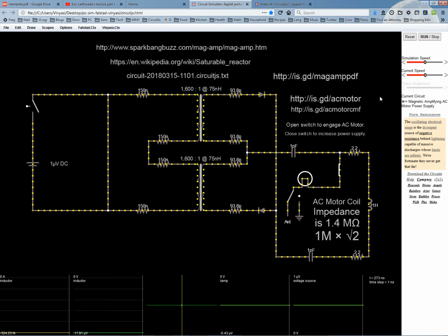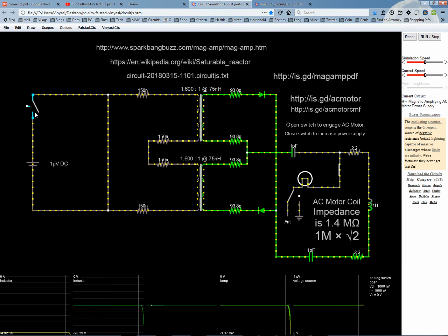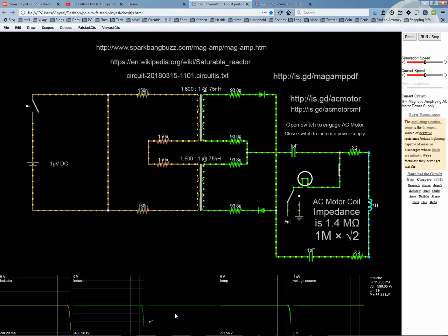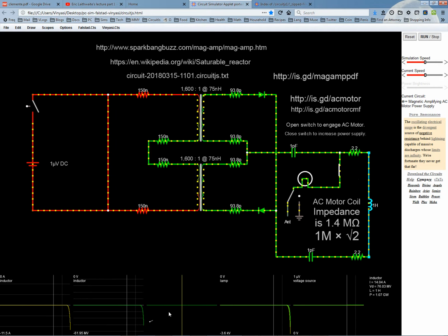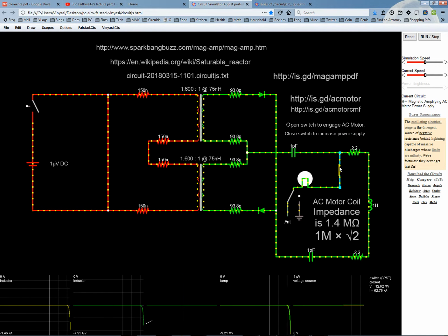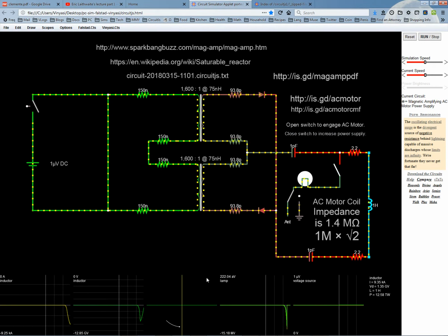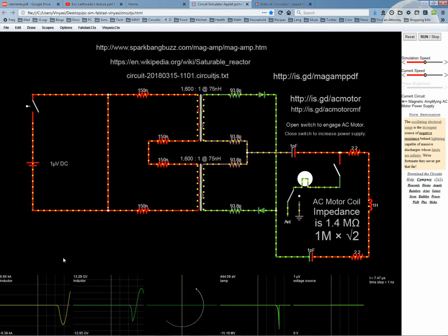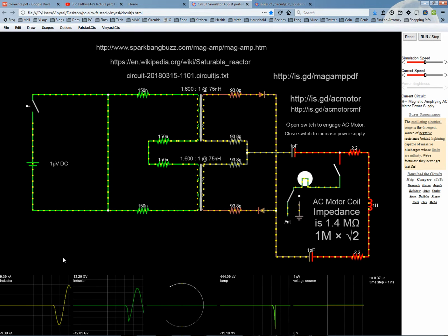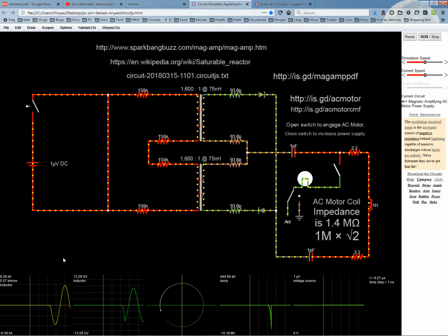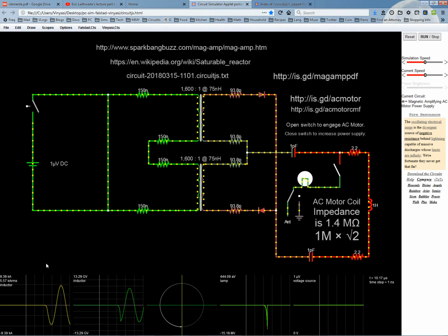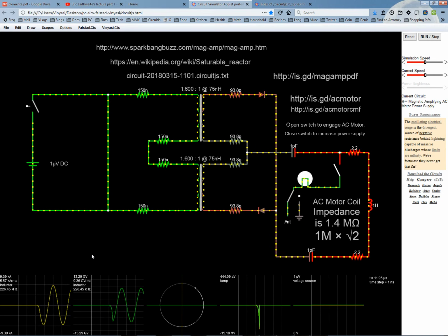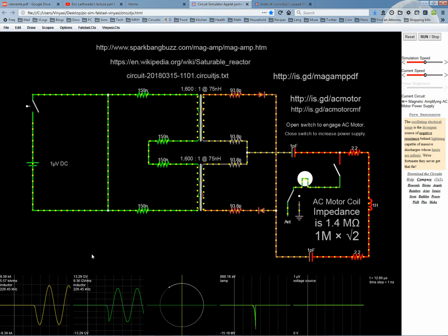So we start it up, and immediately it pops over to the aerial, and the battery pops open, disconnecting the battery. And you see already it's surging in the negative direction. And our V over I is showing negative resistance here. So we'll pop this open. And now we see that the inductor turns into a nice, smooth, well-defined sine wave. And in a moment, we'll find out what the RMS is and the frequency. There it goes. So we've got an RMS value, and we've got a frequency value. And that'll only happen if it's a clean, distinct, singular frequency.